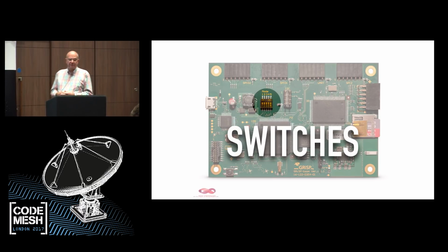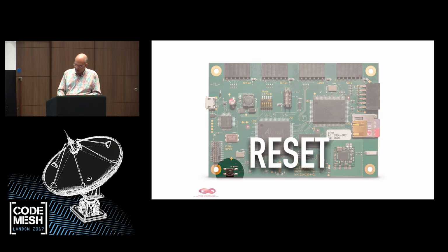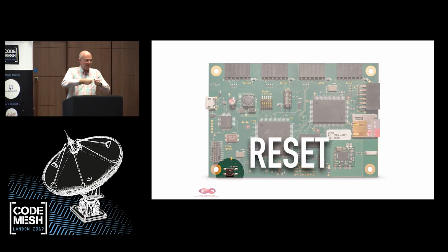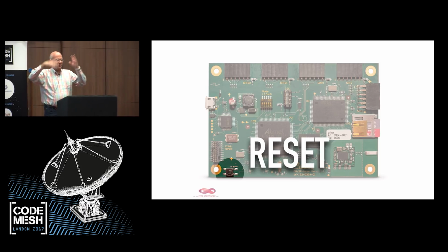You also want to have maybe a few configuration switches or input switches to play around, or to actually start the server. I didn't implement that. You could have used that for the robot to basically say, okay, now stop moving, sleep. 5 switches. You have a reset button, which is always very convenient during development. Reset is very much nicer than unplug, plug, because if you unplug, plug, then your serial line goes off, and that's not good. So reset button.